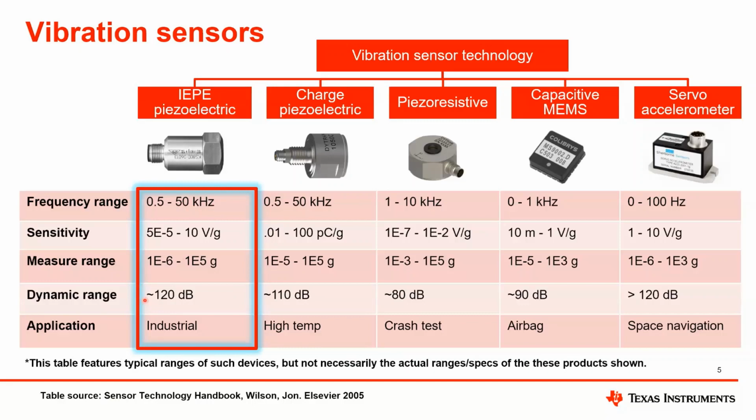The reason for these highly demanding requirements is that the sensors are typically attached to machines or equipment in a very noisy environment regarding vibration. So the spectrum is full of non-essential tones and vibrations which are not what we are looking for, and we need this high dynamic range and wide bandwidth to allow us to dig into the spectrum and pick the tones that matter to the specific machine health.